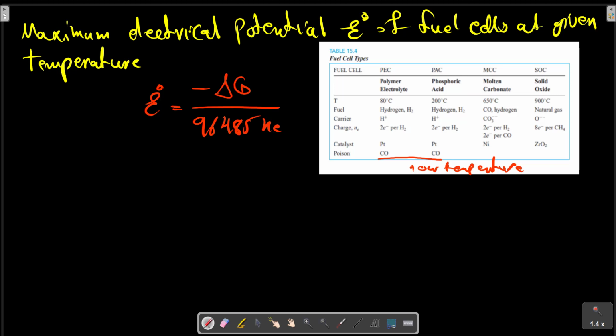The latest research is being done with gasified coals as a fuel and operating the cell at higher pressure, like 15 atm. As the fuel cell has exhaust gas with a small amount of the fuel in it, additional combustion can occur, and one can then combine the fuel cells with a gas turbine or steam power plant to utilize the exhaust gas energy. This combined cycle power plant strives to have an efficiency of up to 60%.